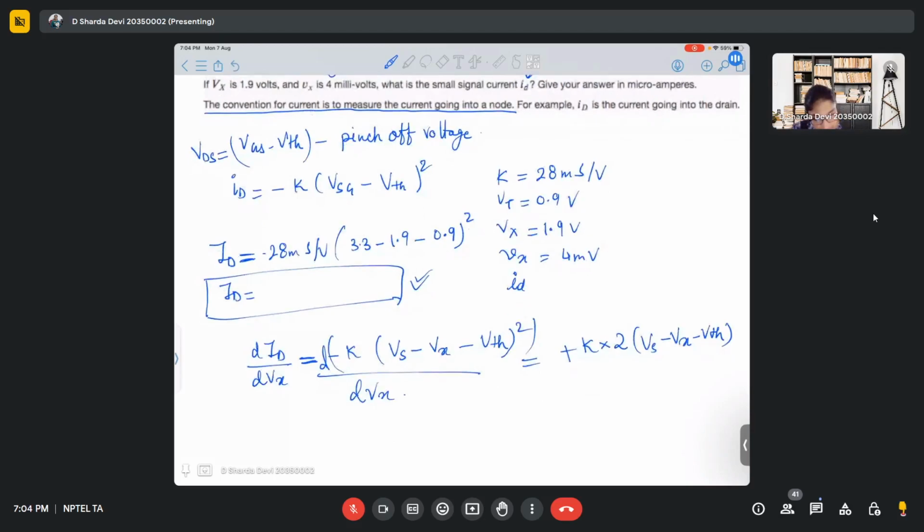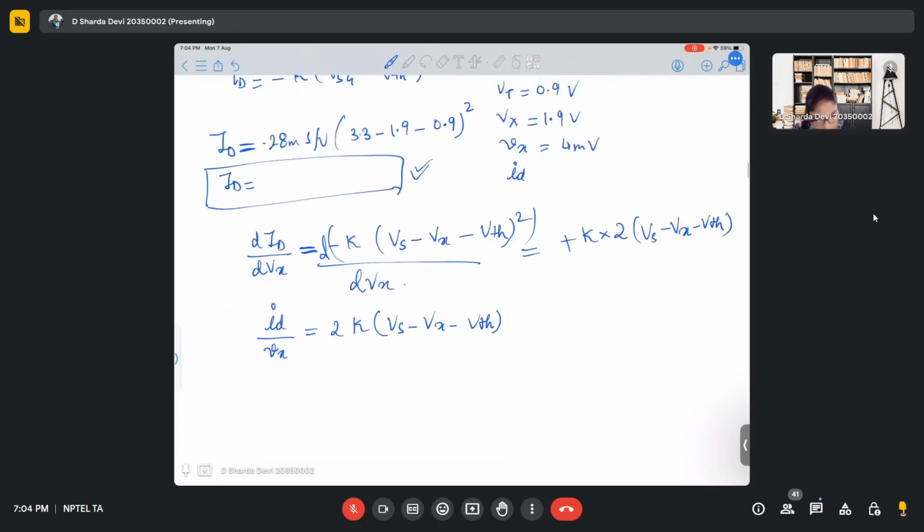This small change in ID is our small id, which is asked in the problem, and the change in Vx is the small vx that has been applied. So the small id will be 2 into k (Vs minus Vx minus Vth) into small vx. So small id is 2 into 28 millisiemens per volt, 3.3 volts minus...